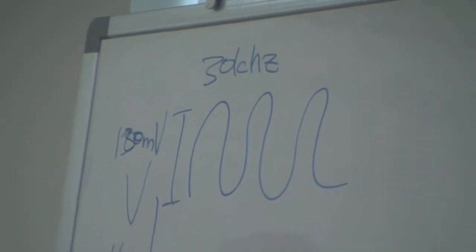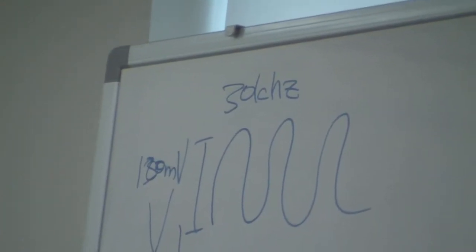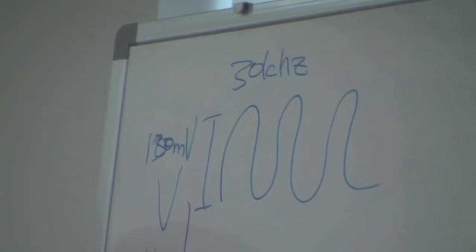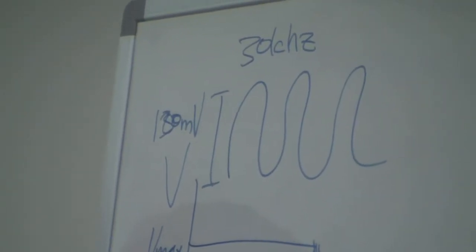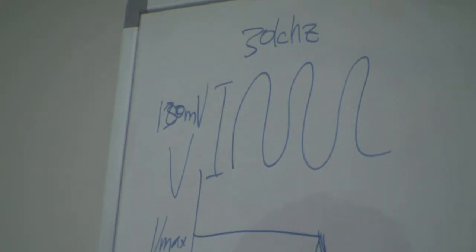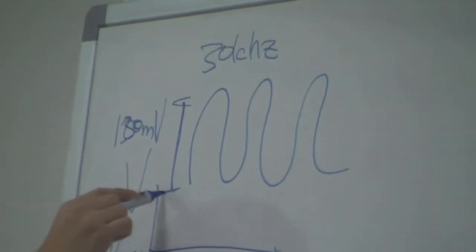Okay, 30 kilohertz. For 30 kilohertz, if you have the basic modules in there, most likely that's not going to reach 30 kilohertz. These are probably limited at about maybe 500 hertz or 1 kilohertz. But the amplitude is definitely possible, so this should be no problem for the amplitude. But 30 kilohertz is a little bit above the capability of this module.